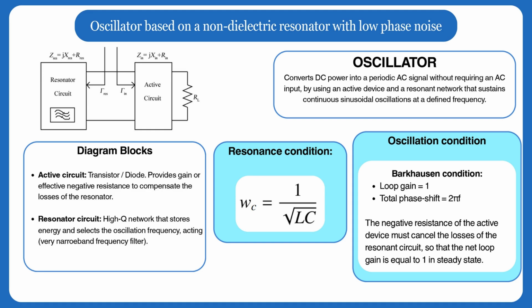To achieve low phase noise, we maximize the resonator Q and use a low noise active device. In our design, this will be accomplished using an air-filled coaxial cavity resonator, which will be described in the next slide.